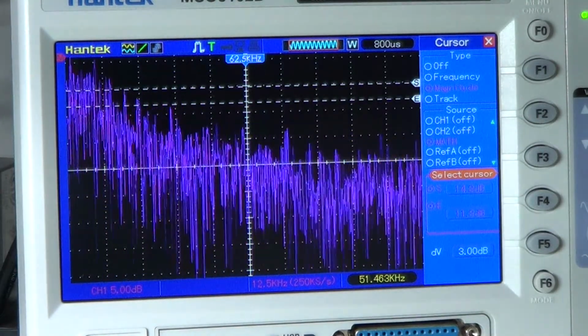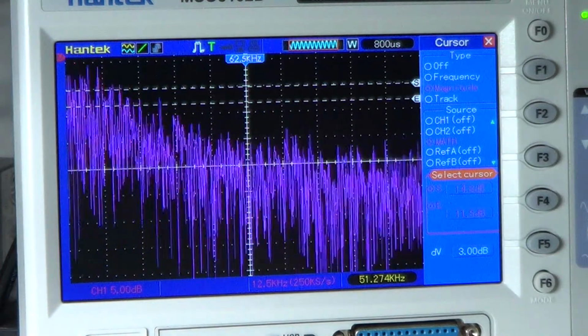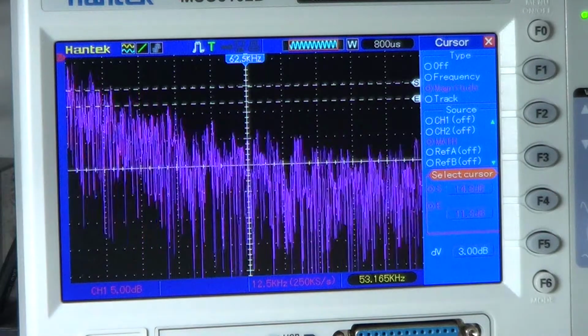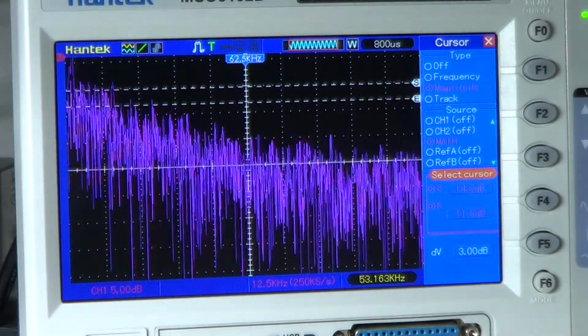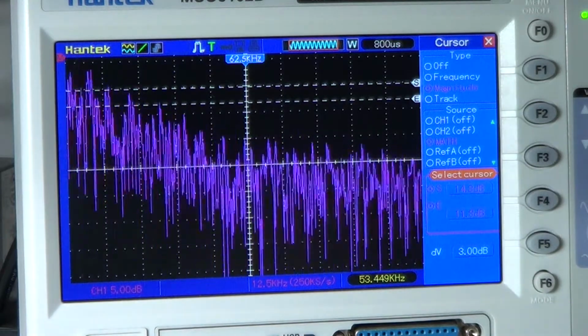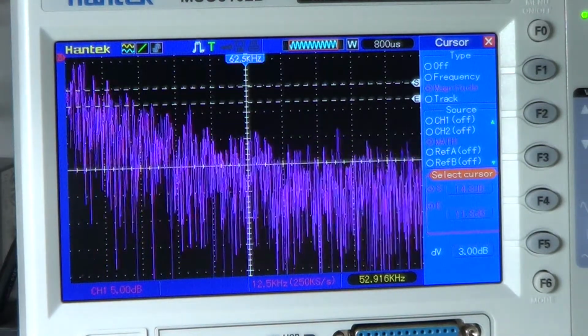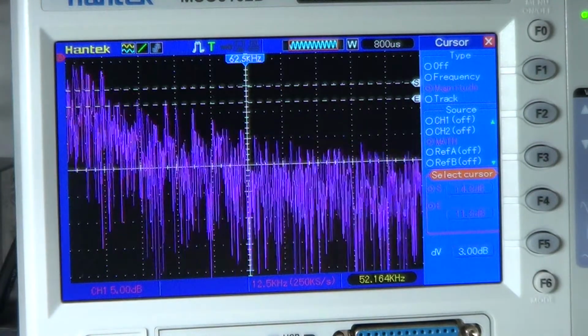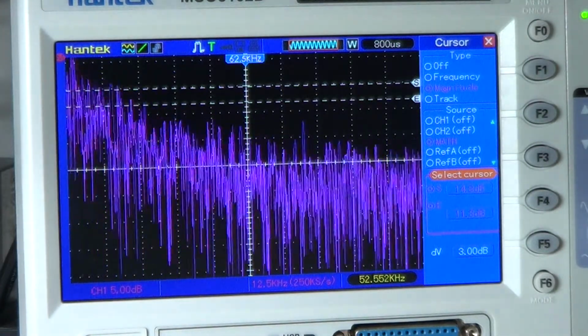I mean, 6 dB per octave, for example, corresponds to about 20 dB per decade. So if we measure one, we have also the other. If you are more concerned with the actual scales of frequency, you use per decade. If you are more into filters for musical instruments and so forth, you may want to use dBs per octave instead.